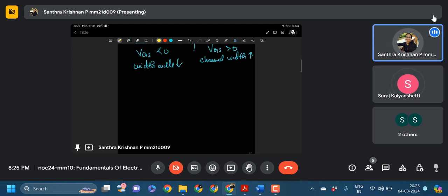Here they have the condition of strong inversion. And finally, they want us to calculate the hole and electron concentrations, right? So PS and NS. Ni squared by PS we can do. For PS we will have to use the equation which involves phi B.